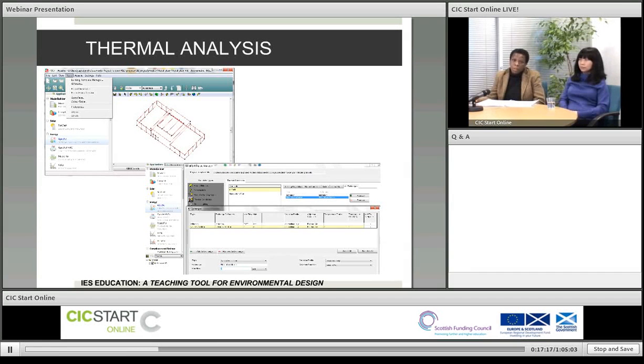So they could take, say, the model with the obstructions. We had about 5 different models. One was with the windows all closed, one was with the windows 50% open, and one was with the windows 30% open. But they could also, for example, change the profile of the cladding, so you could have either a high U value, a very well-insulated building, or a very poorly insulated building.